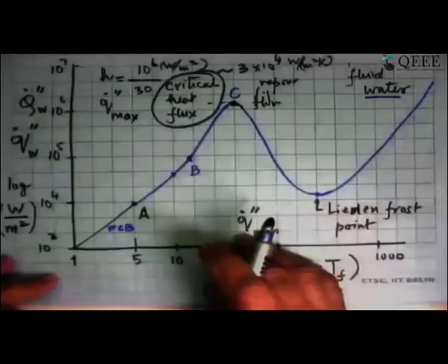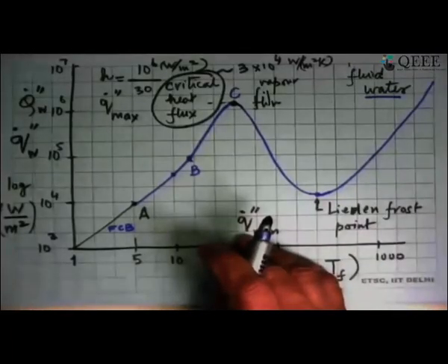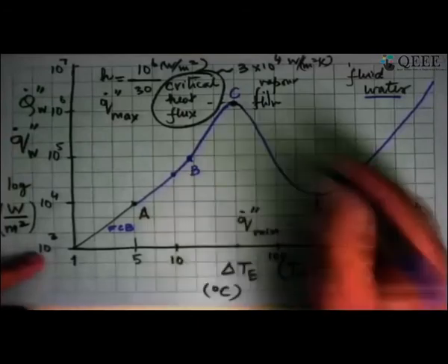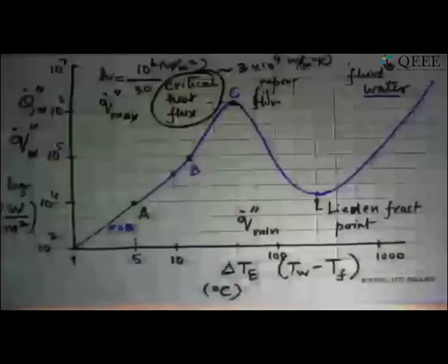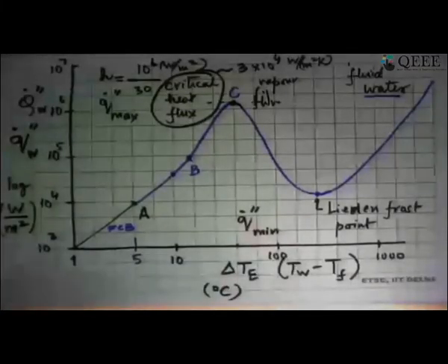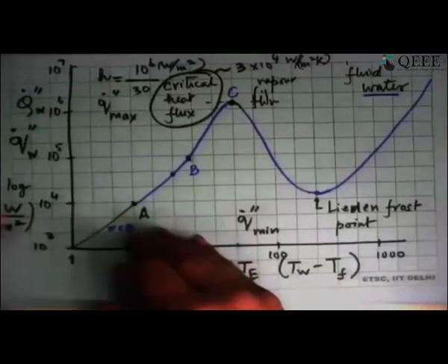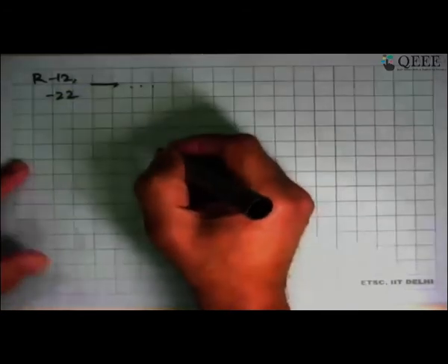The thing is that this is for one particular material that I have shown. As you start looking at newer and newer materials, you have to redraw and redo this whole work, regenerate this data, and then use that data in engineering design. This is what has happened in the world of refrigeration and air conditioning, where due to climate change aspects, you have to get rid of the older refrigerants like R12, R22, then some other refrigerants came in, and now even they have to be phased out, and you are looking at 134a and more refrigerants coming in.